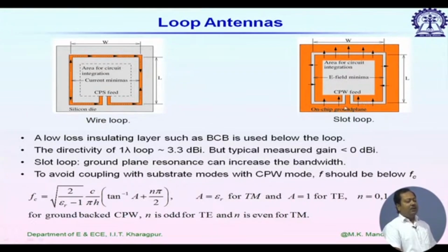The advantage is that the outside ground plane is really narrow and it can be used as a second radiator. So, that means as if we have two coupled resonating structures, which increases the bandwidth of this antenna. This type of technique is very common for bandwidth improvement of any antenna.